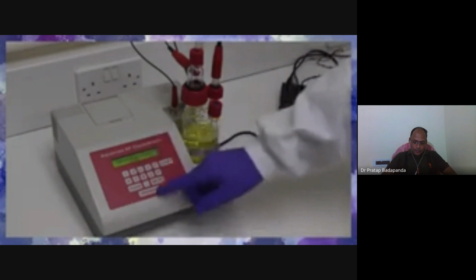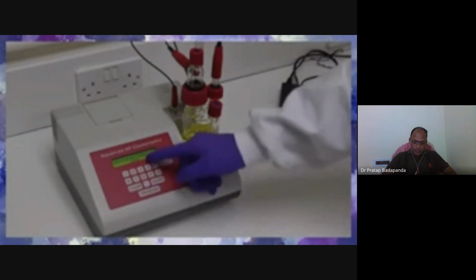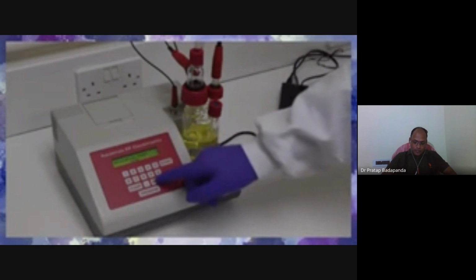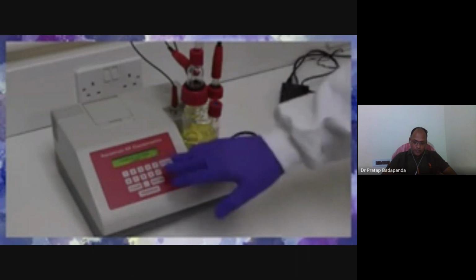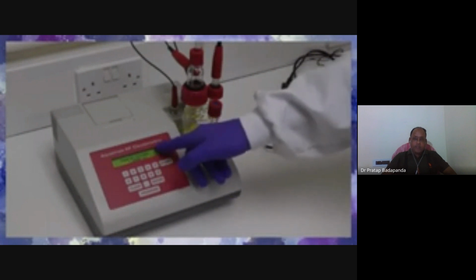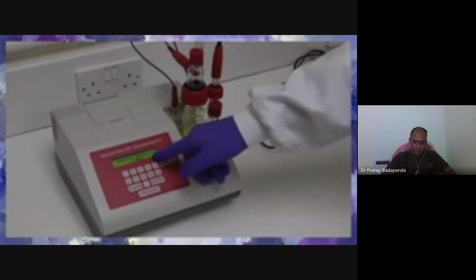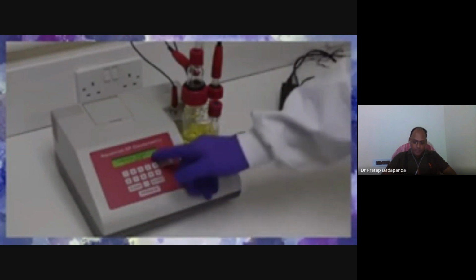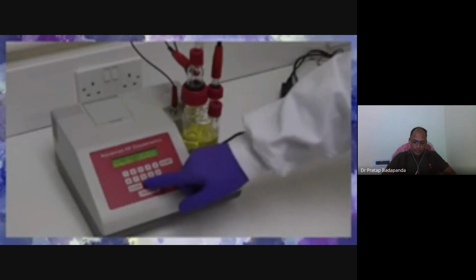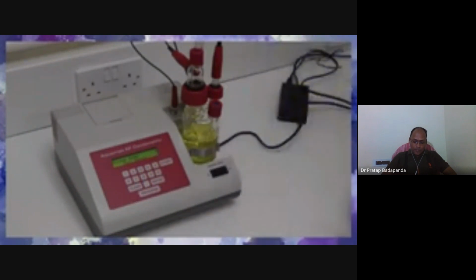This is calculation mode. The choices here are volume and specific gravity, volume, weight difference, weight, and dilution ratio. The Aquamax KF moisture meter will then ask for the values appropriate to the chosen mode. The printer mode parameter gives options for off, for printing every result, or for a full report including time, date, sample number, instrument serial number, and so forth.